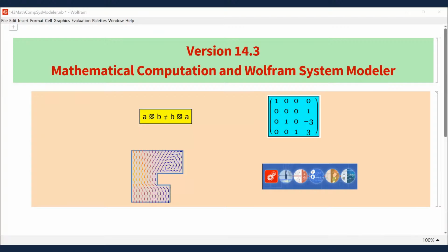I can quickly comment on the PDE aspect of it. That's not ray optics, I understand that, of course. For ray optics, I think Optica is still the thing to use. From the PDE version, we have material in the electromagnetics area. What we still lack is a prepackaged full Maxwell equation setup.